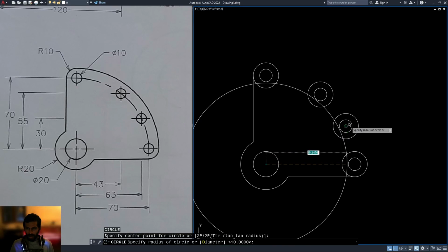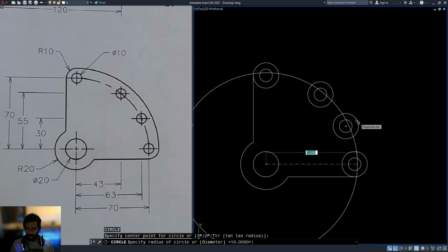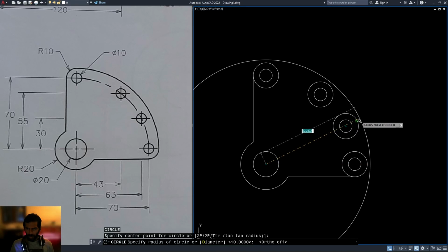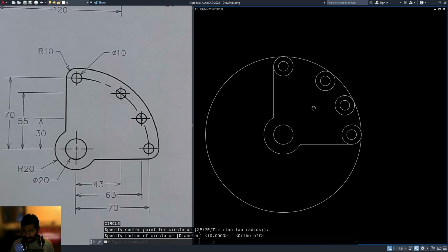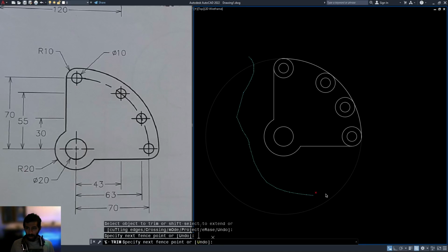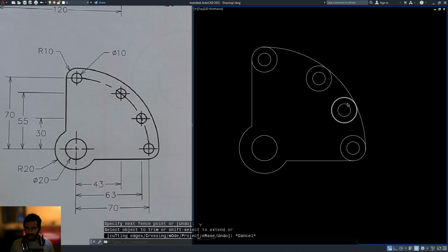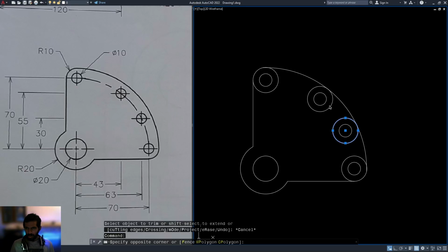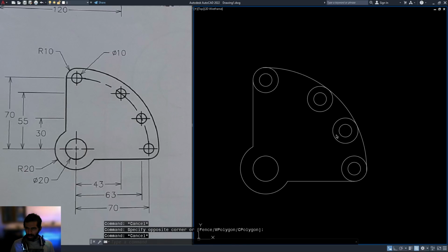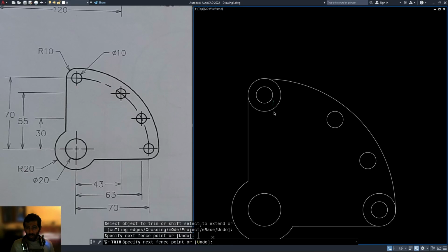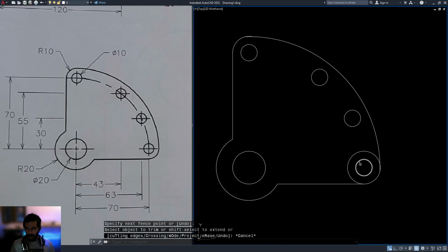So draw up a circle, and maybe I can turn off ortho. I can draw the circle right in there. Okay, that's clear. Now let me trim it. This line is no longer needed, and you can remove these circles, which were drawn for reference. I can remove these circles, just delete them. Finally, we don't want to have this. I can trim it. Now this one is also an unwanted asset. You can trim it.